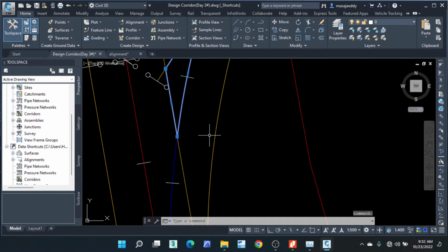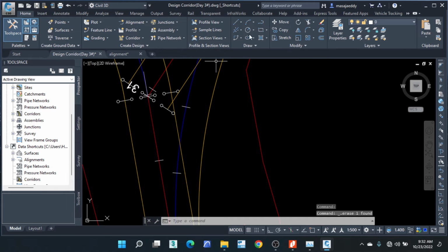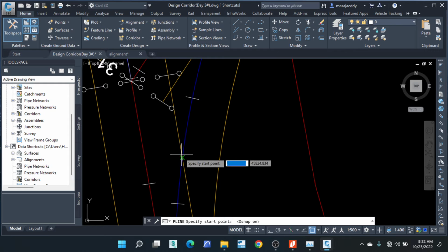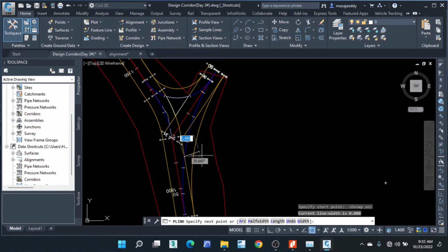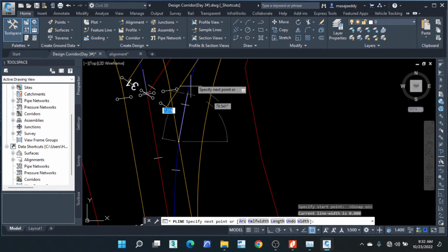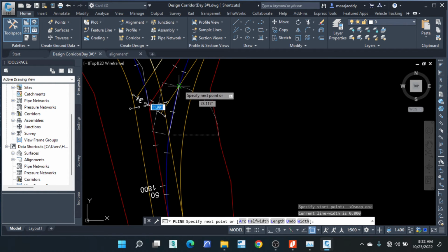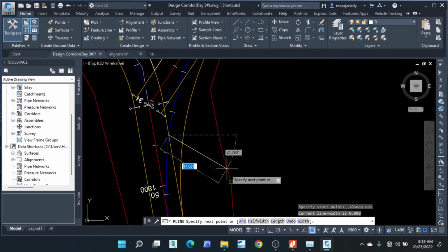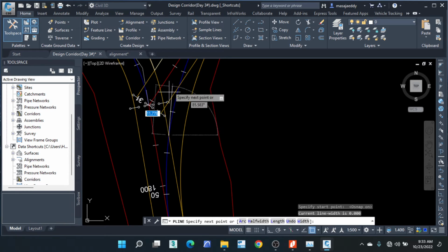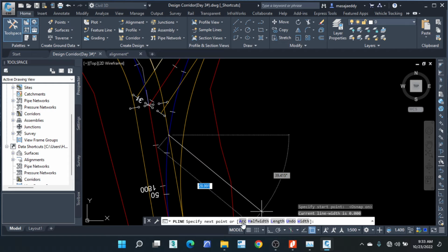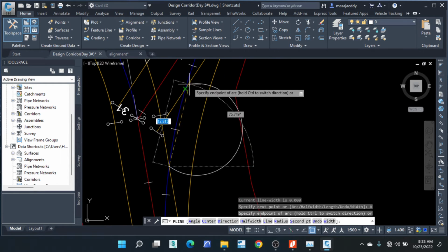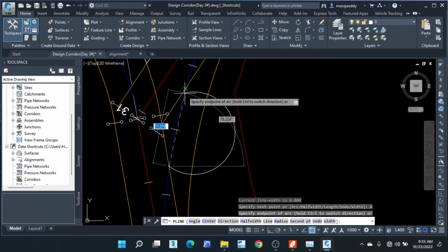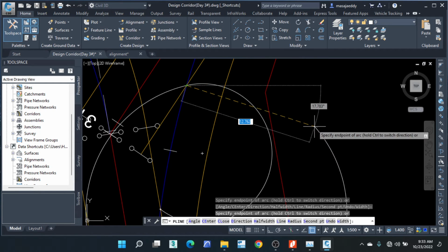So I'm going to delete this. Okay, let's draw together. Click the polyline. Make sure your snap is on. Snap at the beginning, one of the sides, right? So it depends, this side or this side. We can start with this side, right? So once you start with that side, this is a little bit of a curved area, so we are going to use arc. So once I'm done, I'm going to connect this point where this other alignment is connecting to the offset alignment, that area.